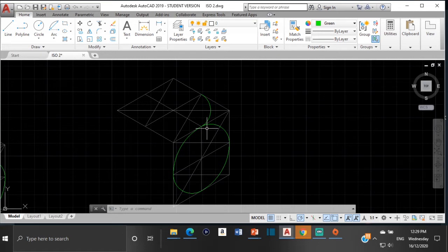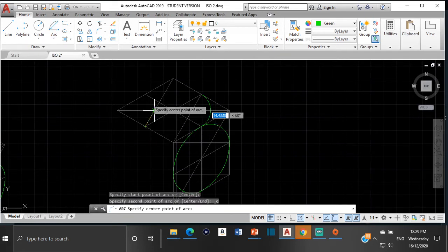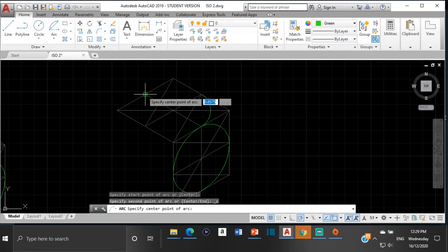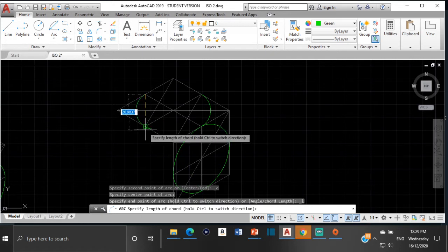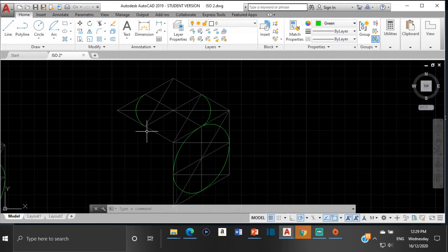Okay, now to get this next quarter down here, we select start center length again. We can start here, use that as the center, and that's the length. All right, it's got itself in the wrong direction, so start here, use this as the center, and then that's the length right there. Okay, start center length. Good. All right, and now again, if you're doing it on paper, compass point here, open it to there, and scribe your arc.